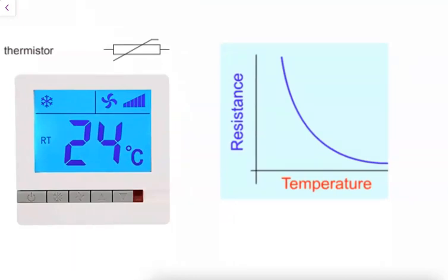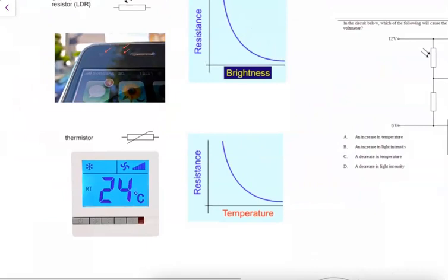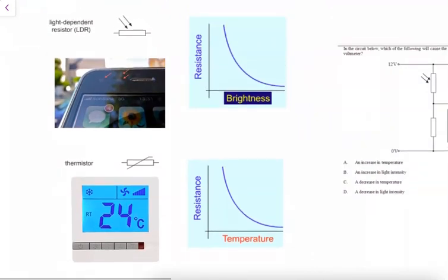So again, similarly, it reads the temperature; its resistance changes based on the temperature. There must be a voltmeter or somehow it reads the voltage across this thermistor to help us determine what resistance it has, and then determines the temperature. And then there must be some programming involved to make this happen. So one thing, as brightness increases in a light-dependent resistor or temperature increases in a thermistor, the resistance will